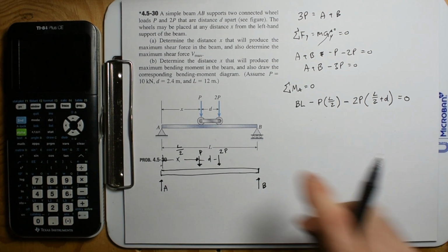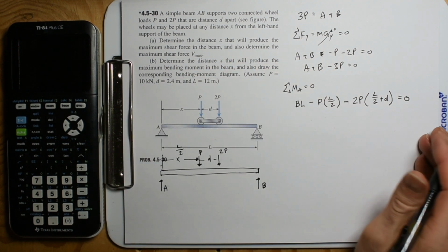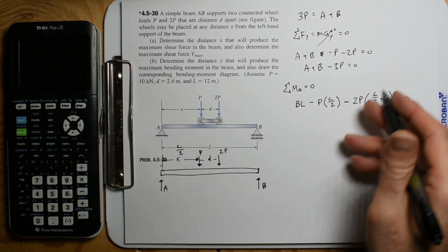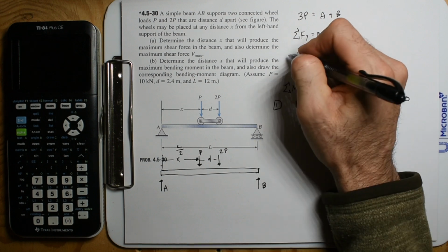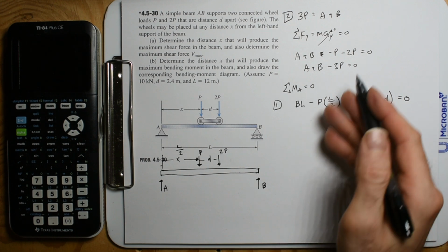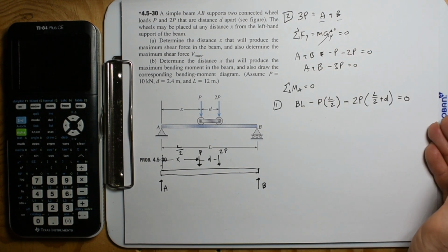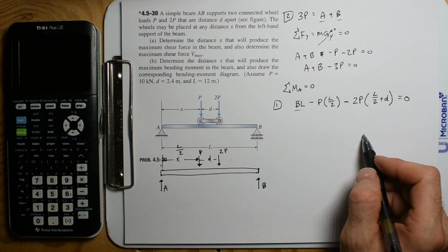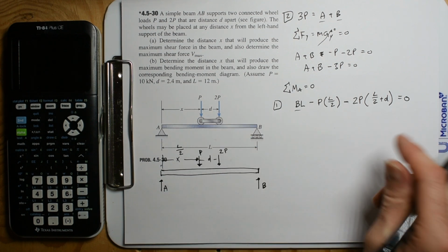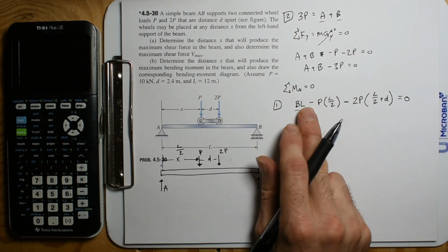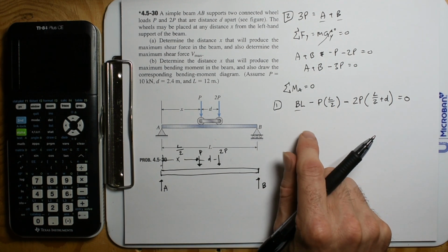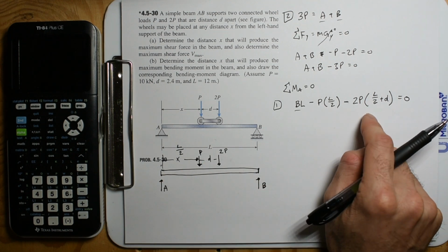Now, from our problem statement, we probably should just put numbers to this, but I guess we're not. But we have an equation here, and here's our other equation. This is the equation in the y. The things that we do not know are A and B, and we have B right there. We do know the load P, that's going to be given. We know the length, we know this distance D, and so everything else is known. So we can solve, and this equation just solves for B. So that's kind of cool. The sum of the moments about point A, solve for B.